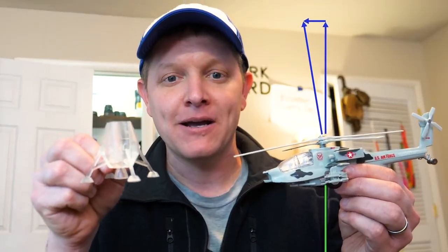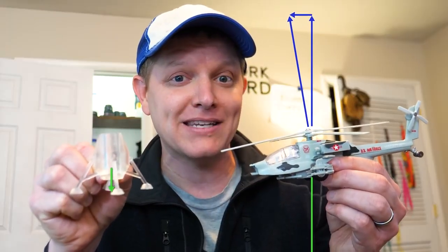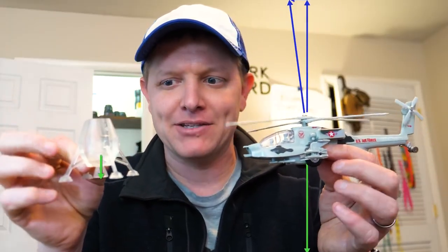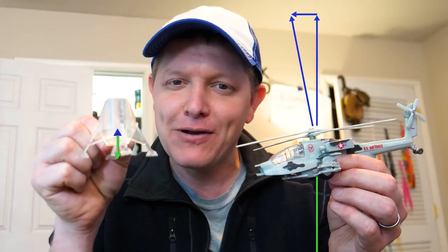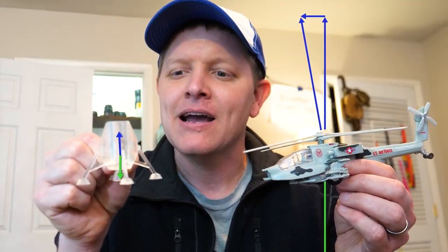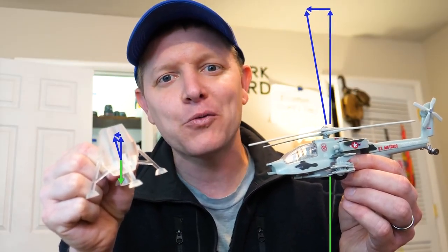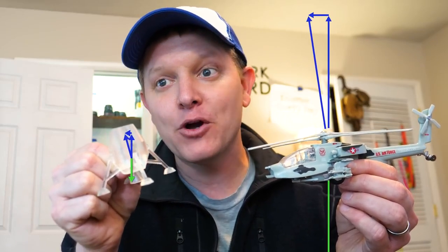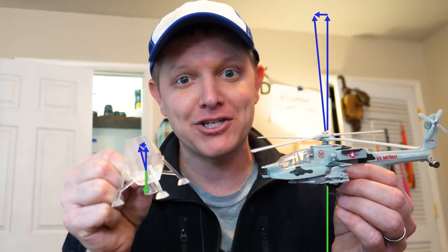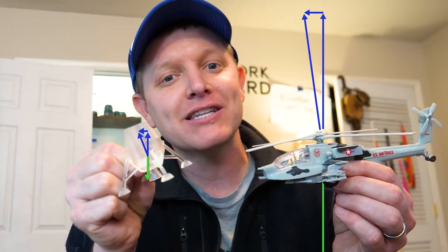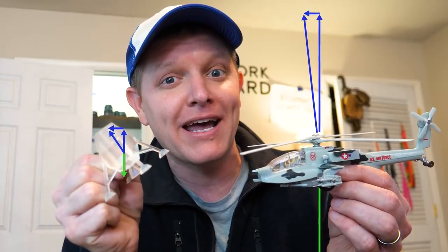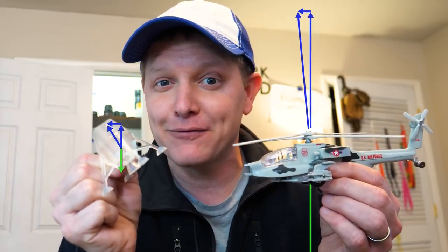Now that makes sense on Earth, but the problem is if you're in a spacecraft and your spacecraft has 1/6 the weight of a helicopter, even if they're the same mass, you have to go with me here. Think about it. If you have a very small thrust required to lift that thing, if you tilt it over and try to translate with the same acceleration moving forward, it's not going to work, because as you tilt that thing forward, the horizontal component of your acceleration is far lower because you're not thrusting as much. So in order to get the same acceleration in the horizontal direction, you would have to tilt the spacecraft over much farther than you would a helicopter. This is the problem they had to figure out how to solve.